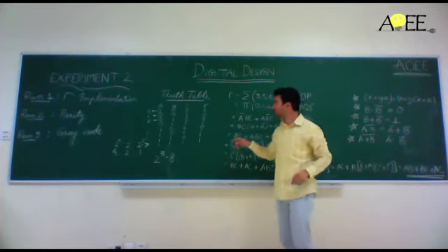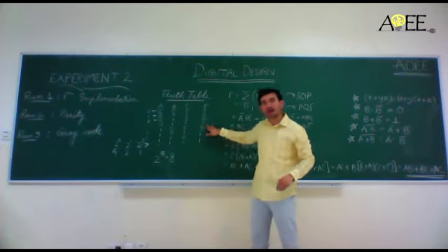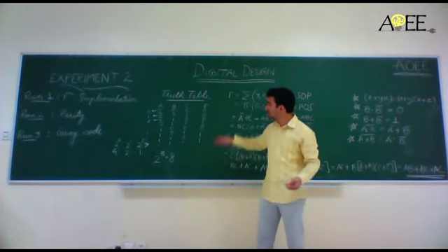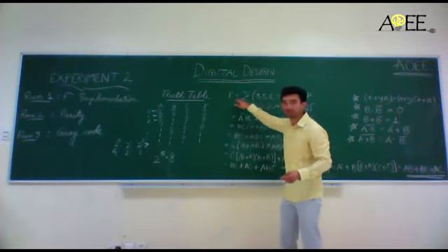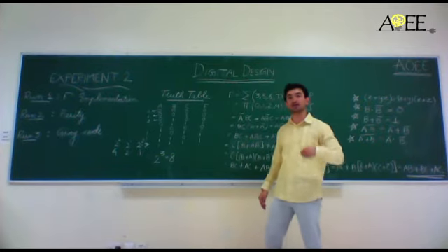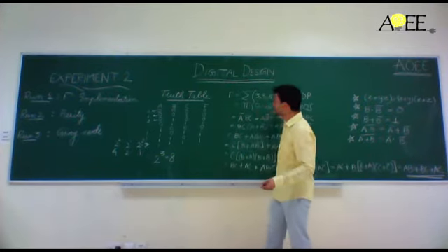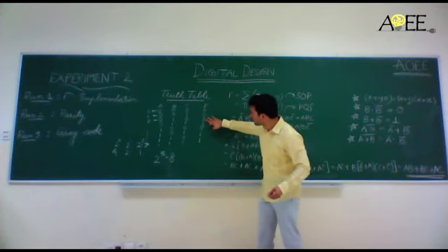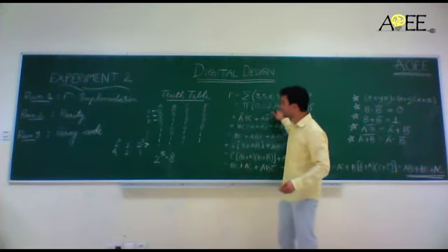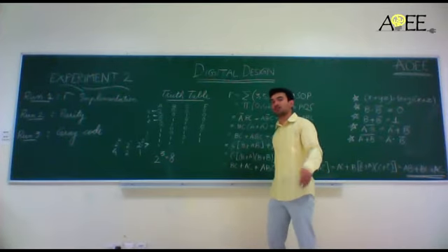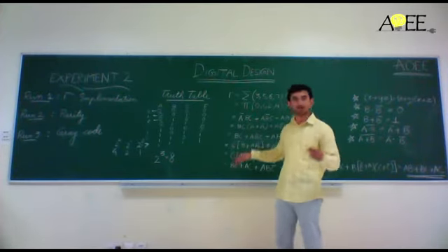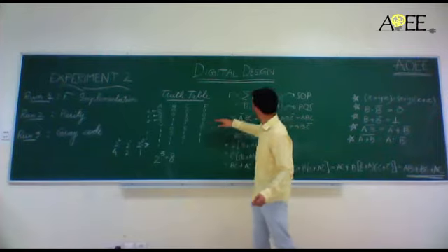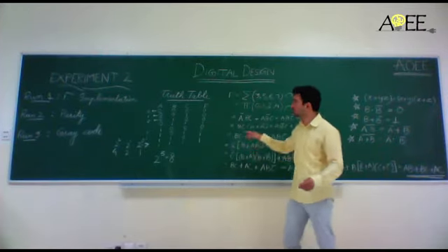In sum of product form, whatever outputs are high, meaning 1 in the function, are written in the form of sum, and whatever outputs are low are written in POS form. So POS form will have 0, 1, 2 and 4 in the function writing format, whereas the SOP form will have 3, 5, 6 and 7.